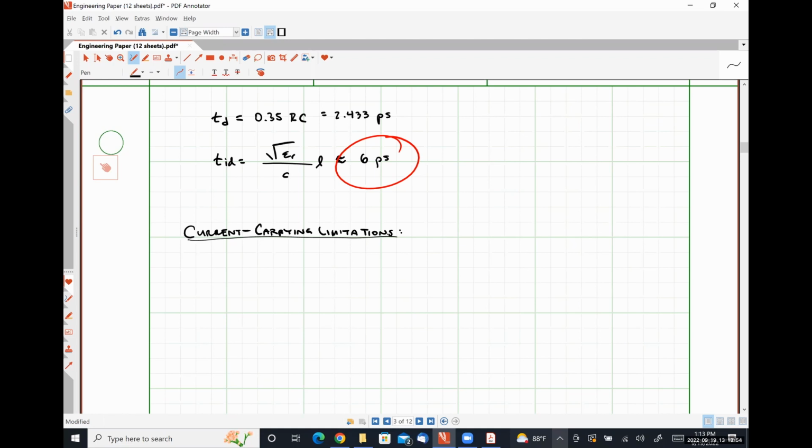These wires in a CMOS device don't have insulation particularly, unless we bury them inside of an oxide layer or anything like that. But what we have to worry about is effectively we're making runs so physically small that we can melt the metal itself by carrying too much current. And in doing so, we can cause the stretch of metal to physically move or deform. And this is called electromigration.